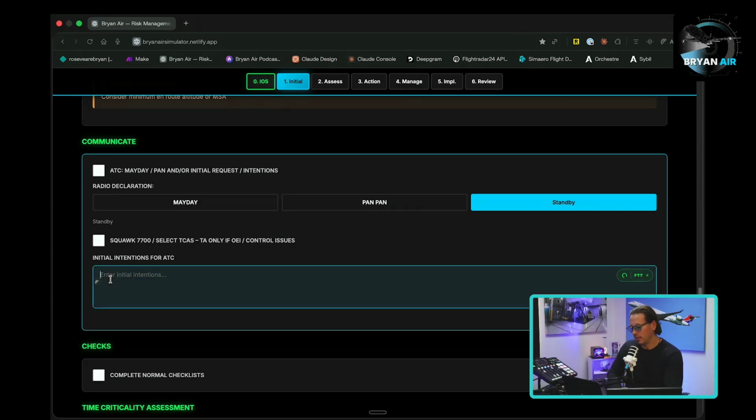But I might need to tell air traffic control something here. So I'll tell them, we are dealing with a pressurization problem and will need to level off at flight level 250.